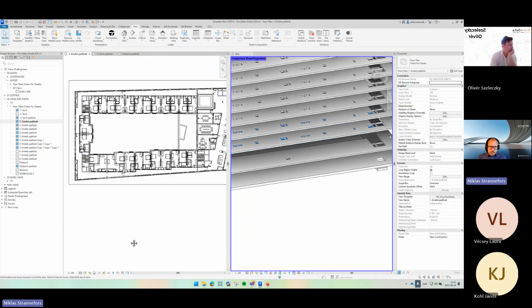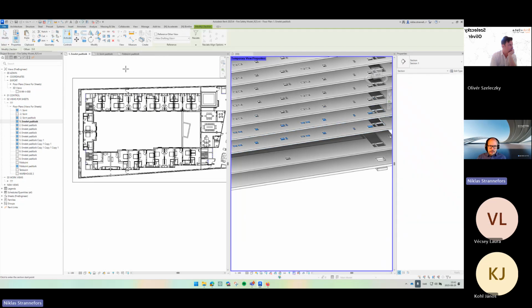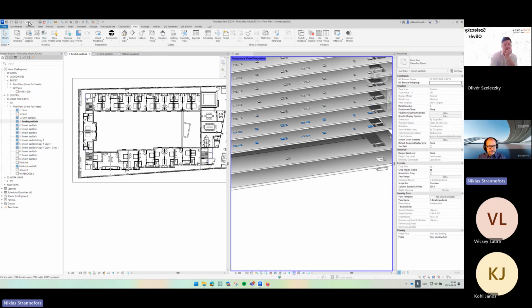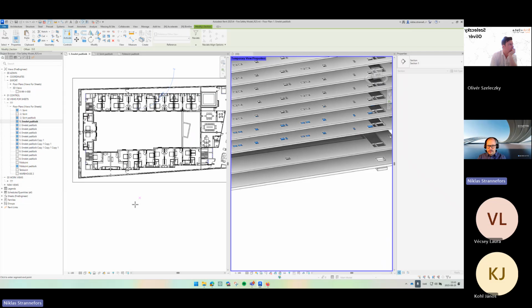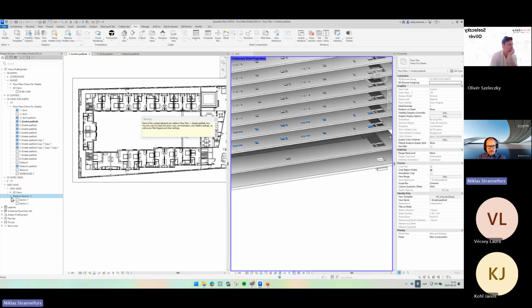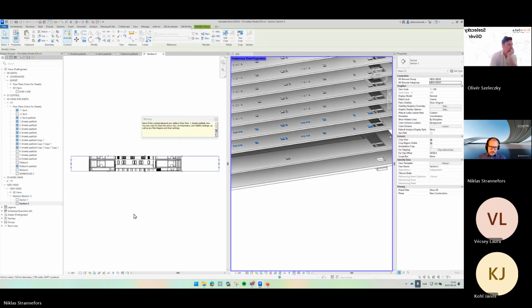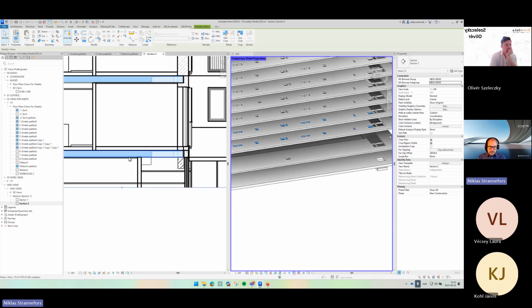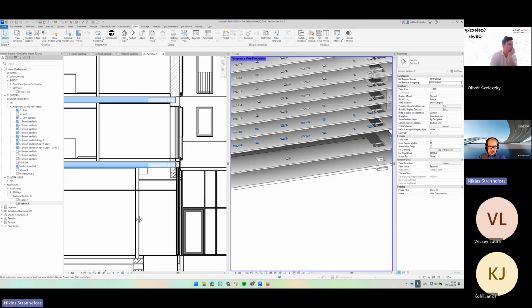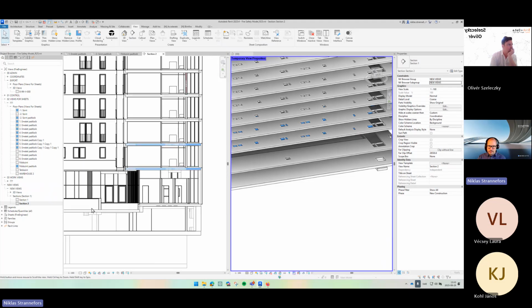Once it's done, we can always create a section right through the model. Going to View, Section, maybe way too fast, I'm going to go back. View, Section, just below View, and you just click twice straight through the model. 1, 2, I'm going to create a section through here, and it's going to appear under new views, sections, section 2, and here we got it. Just going through it, turn the crop off. But here we got our horizontal compartmentation.